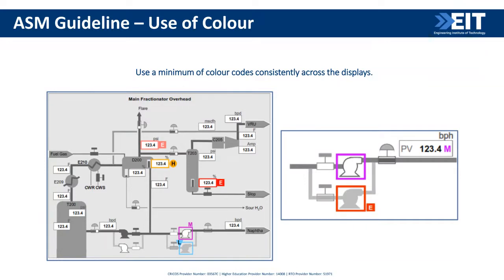So if lines are colored based on the material they contain, then implement the color so they can be toggled on and off. So that's a takeaway. Although it is not recommended, right? But if the operators feel that having the color, for example, if they've got a water line and they want to see a blue color for a water line, give them that feature. But they should be able to turn off the feature.